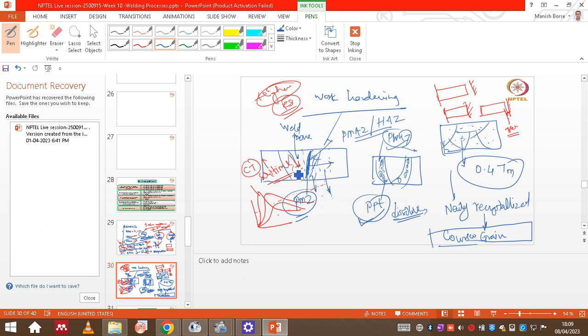change of the initial microstructure of the alloy, right? Let's say the alloy is work hardened, so the dislocation density will be higher in the base region, right? So because of the heat transferred to the surrounding region, these dislocations start annihilating, and processes like recovery and partial recrystallization will take place. In the center region there won't be any problem because here it is completely melted, right?